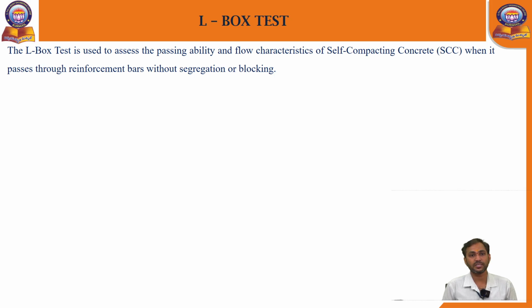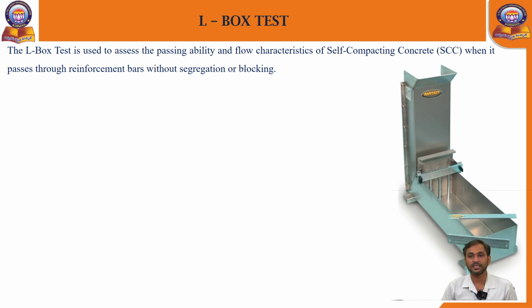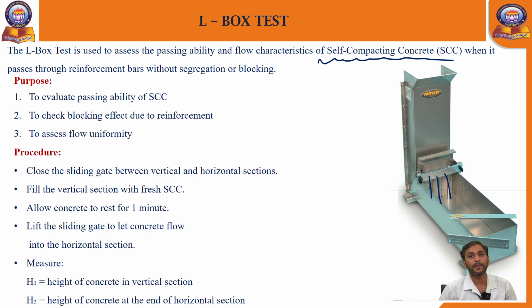Next, the L-box test. The L-box test is best for self-compacting concretes. The L-box test is used to assess the passing ability and flow characteristics of self-compacting concrete when it passes through the reinforcement rods. There are 3 reinforcement bars, without any segregation and blocking. Purpose: to evaluate passing ability.